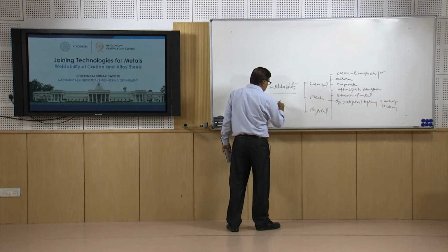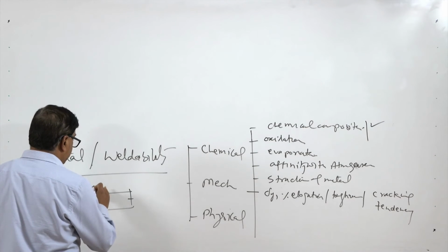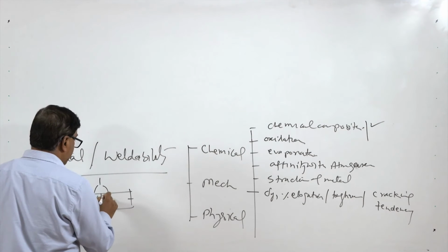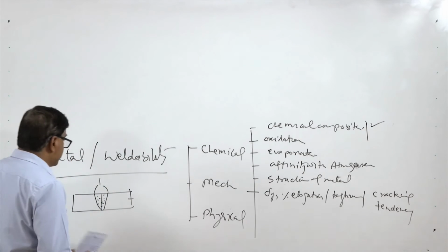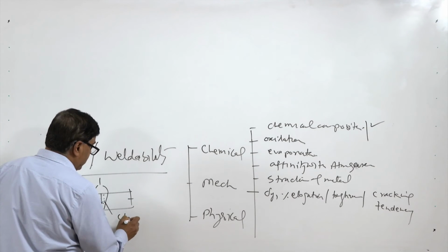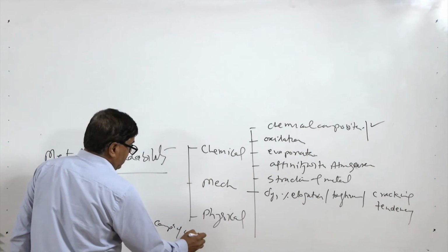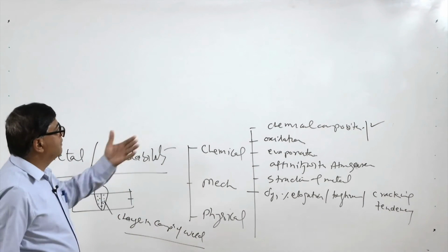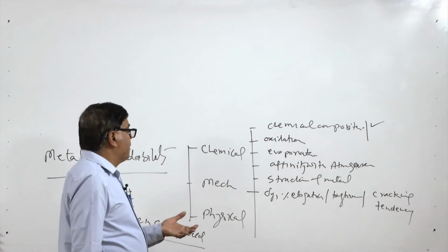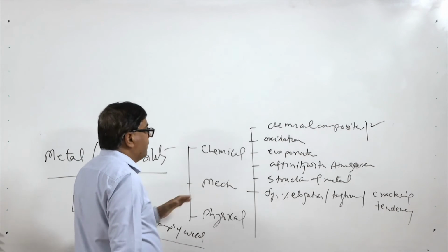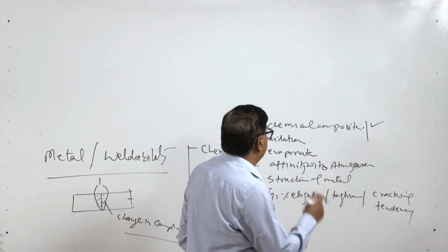Like this is the metal being welded. When it is exposed to the high temperature and the faying surfaces are brought to the molten state, some of the elements will get evaporated, and this evaporation will lead to a change in composition of the weld metal. This change in composition of the weld metal will degrade the mechanical properties, chemical corrosion properties and the tribological properties, etc.